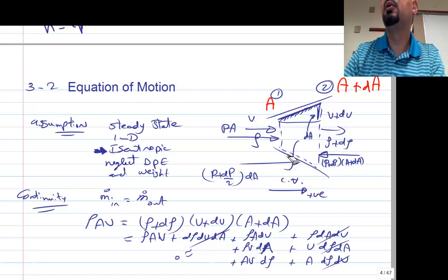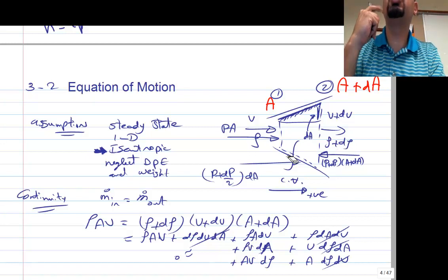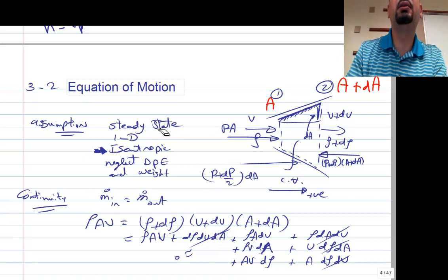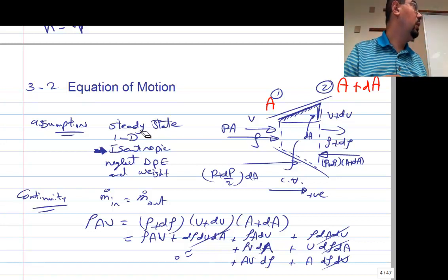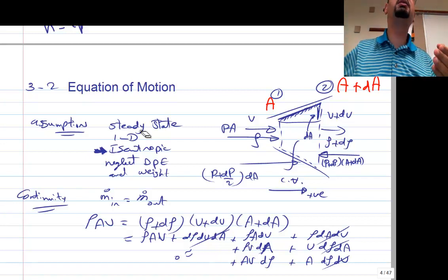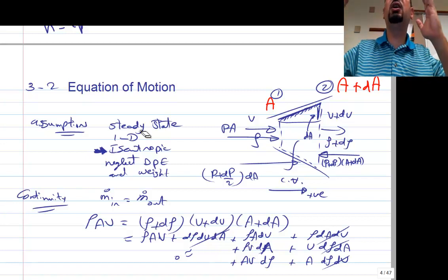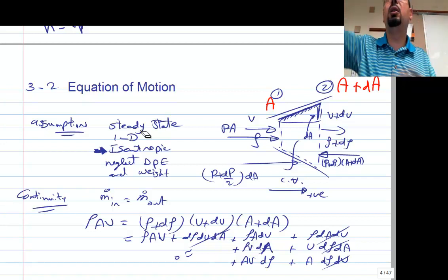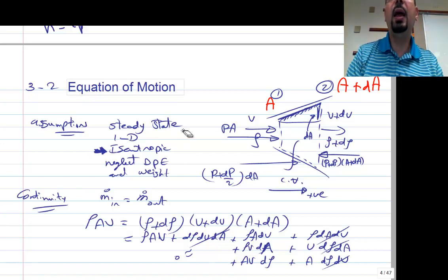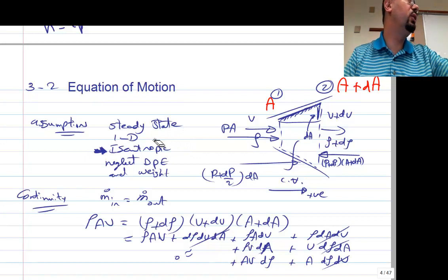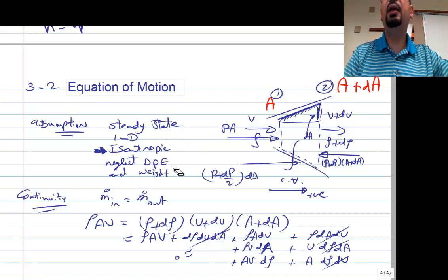All right? Start with the first equation, continuity equation. What's our assumption? Steady state. Yeah, so all those things are supposed to run at steady state. The flow coming in needs to be equal exactly to the flow leaving at the end of the engine. Otherwise, the nozzle will explode, basically, right? So steady state works. And isentropic, we said it's too much to handle the heat transfer and friction at the moment. And neglect the change in the potential energy.